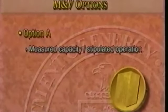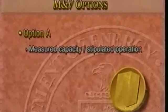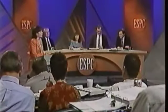The first, option A, is designed for projects in which the performance potential needs to be verified but savings can be calculated based on stipulated operation values rather than directly measured. In other words, energy performance is measured. The actual operation of the retrofit is stipulated based on the engineer's judgment.